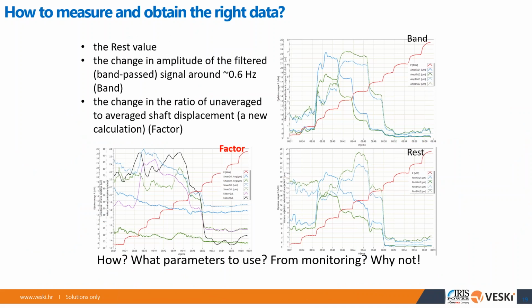So what are the factors that would really tell me how severe things are? You can have different types of vibrations measured, but we have been playing with how to really have one number, so we tested 3 different measurement types and tried to see how they would describe what's really happening in the rough load zone, but not outside the rough load zone. And then we came to this, we call it a factor. The factor is basically a ratio: you take the same signal and process it as you would normally for normal operation of rotating machines, and you get, let's say, a peak-to-peak number.